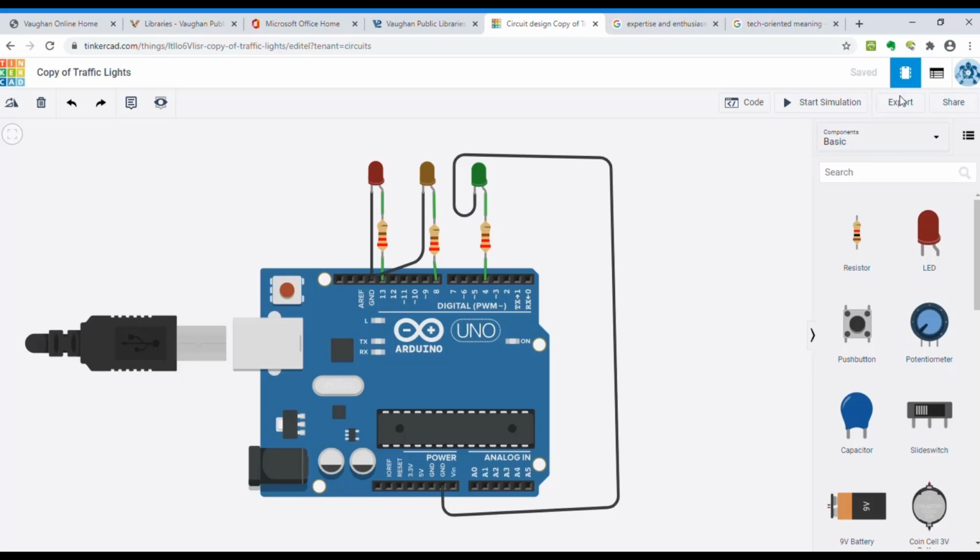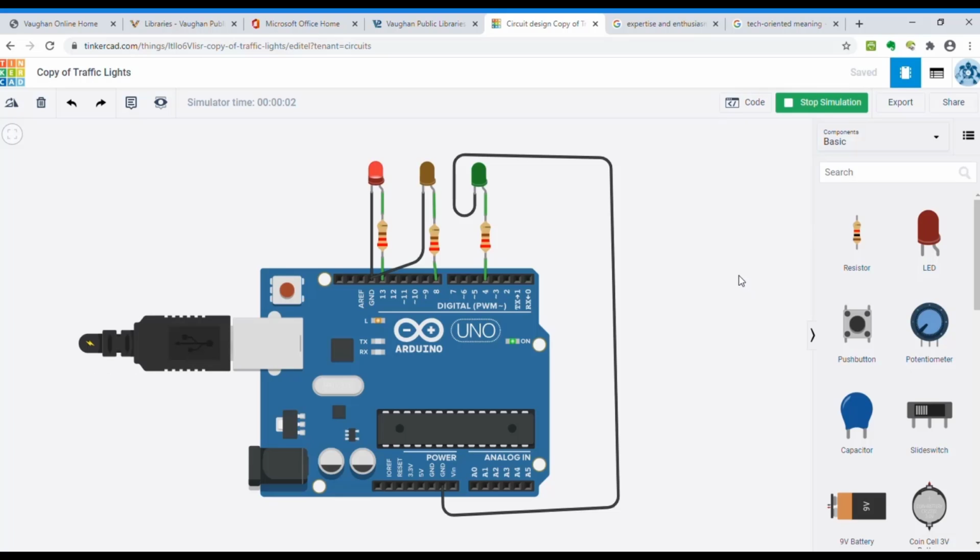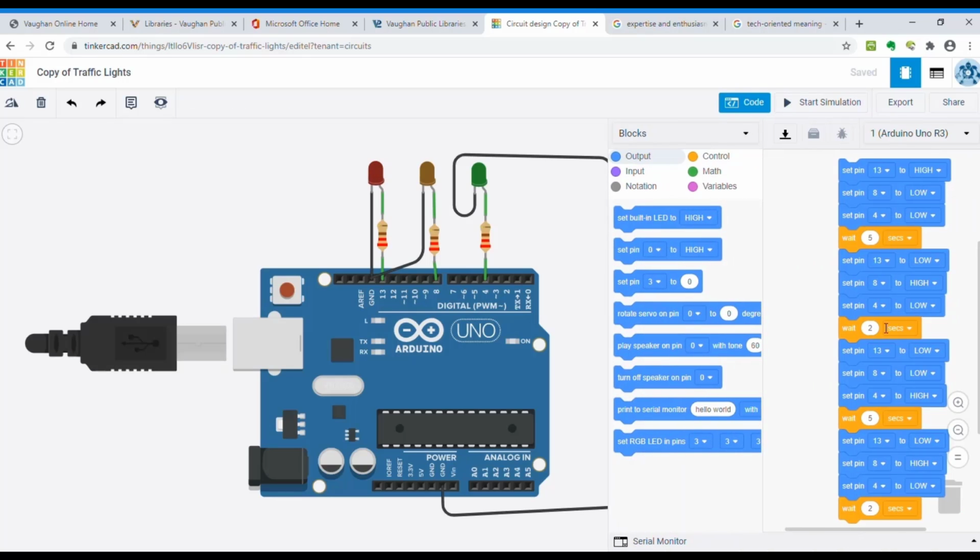It's very similar to the project I'm going to do, but I need more LEDs. Another thing is that for the traffic light, the time for switching from red to orange and orange to red is very long, so I just need to modify those numbers. For example, change the waiting time, which was 5 seconds, to 150 milliseconds.